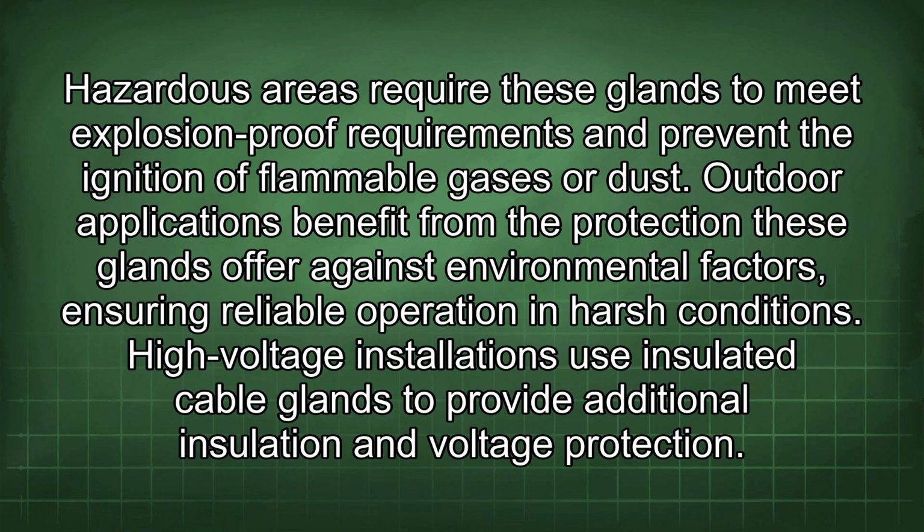Hazardous areas require these glands to meet explosion-proof requirements and prevent the ignition of flammable gases or dust. Outdoor applications benefit from the protection these glands offer against environmental factors, ensuring reliable operation in harsh conditions. High-voltage installations use insulated cable glands to provide additional insulation and voltage protection.